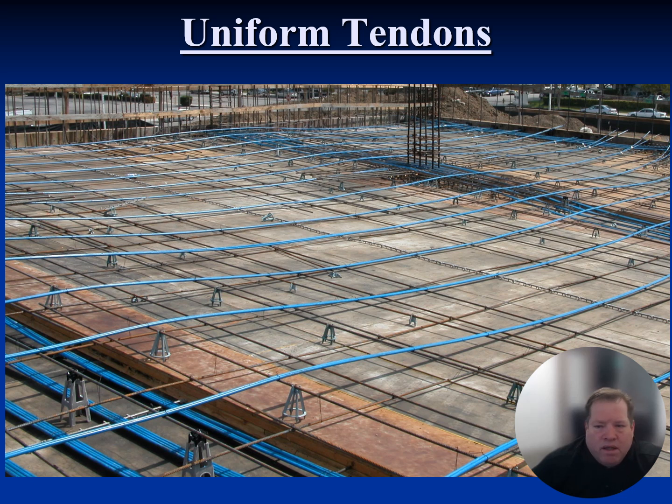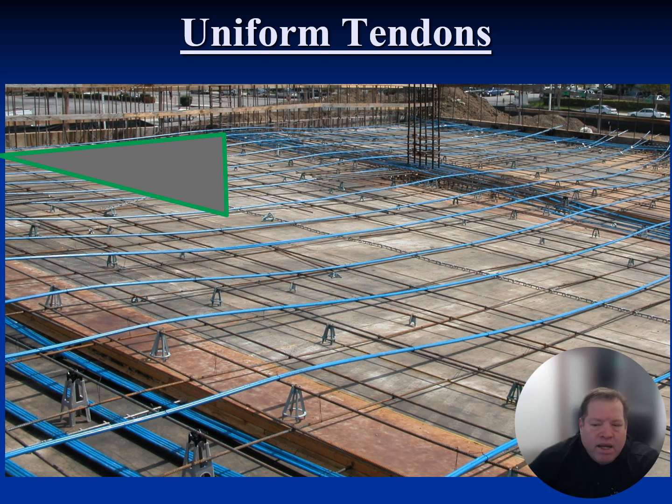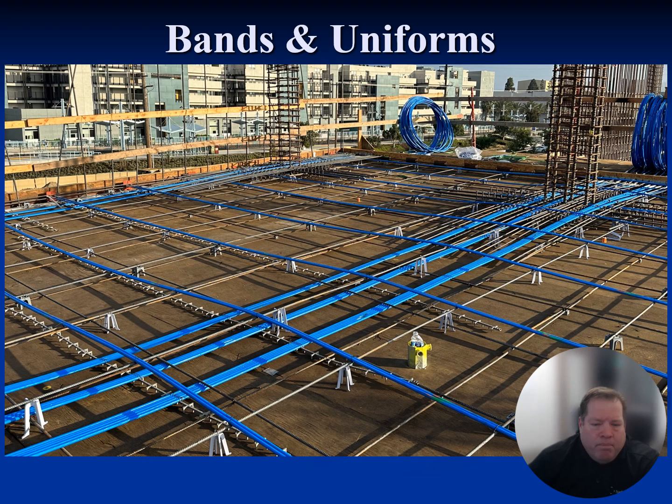Now, the one interesting thing about this photograph, if you're more used to beam and one-way slabs, if this was a beam and this was a beam, you would have temperature and shrinkage reinforcement in the quote-unquote weak direction, which you don't see. The temperature and shrinkage does not apply to post-tension concrete. Now, some engineers don't like it, which again is fine, and so they will put a triangular mat of rebar as the pre-compression from the anchors basically goes into that zone and tries to give you the pre-compression of 100 psi.